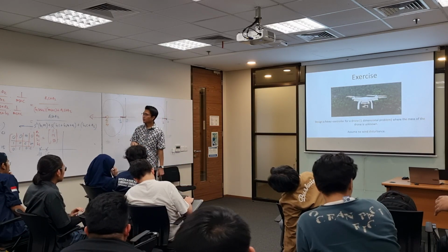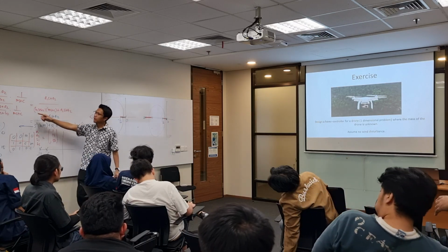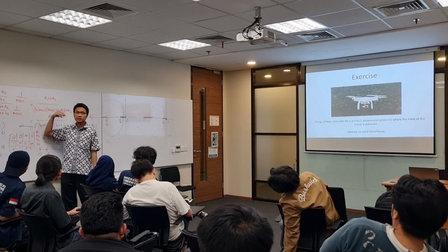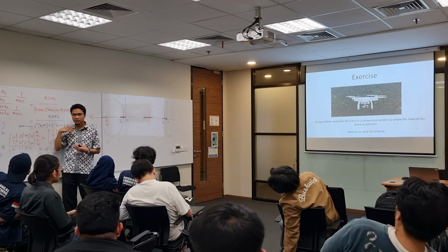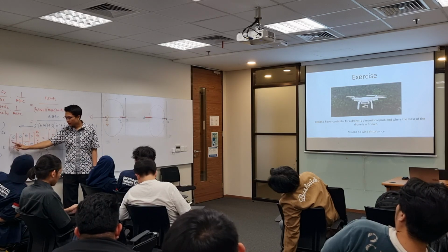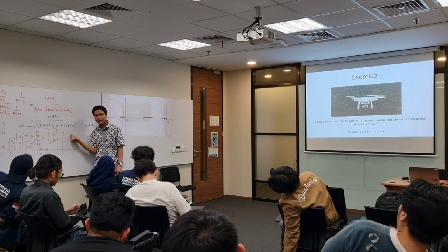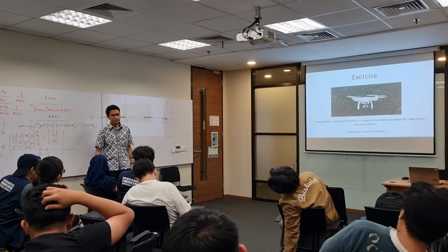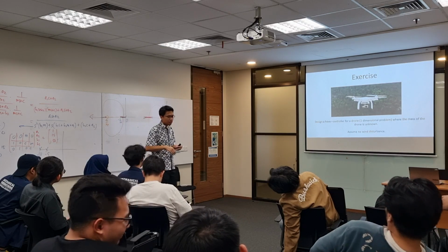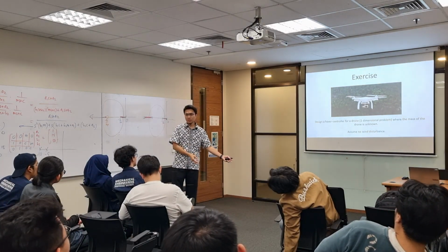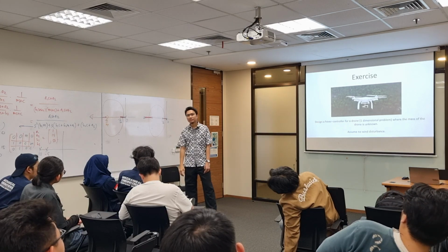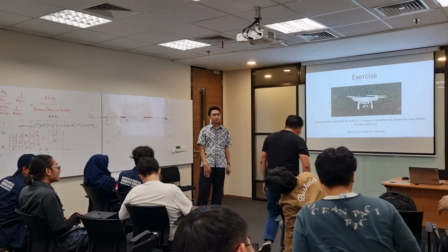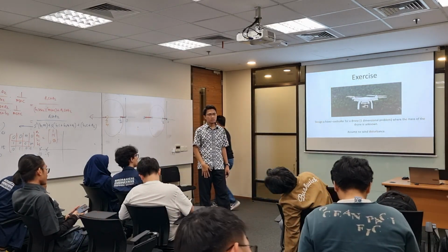Of course, we are modeling it with 1 over ms plus c, right? Maybe the c is different, maybe m is different, so the response may be different also. But at least from here, you have an initial guess, and then you fine tune your system, rather than trial and error of the control parameters, right? So that's the advantage.